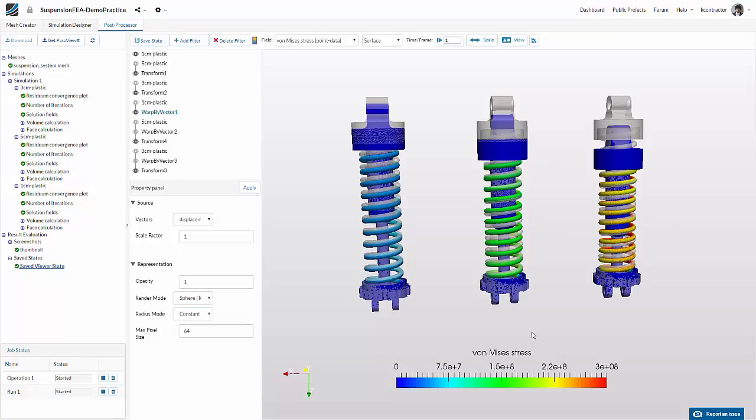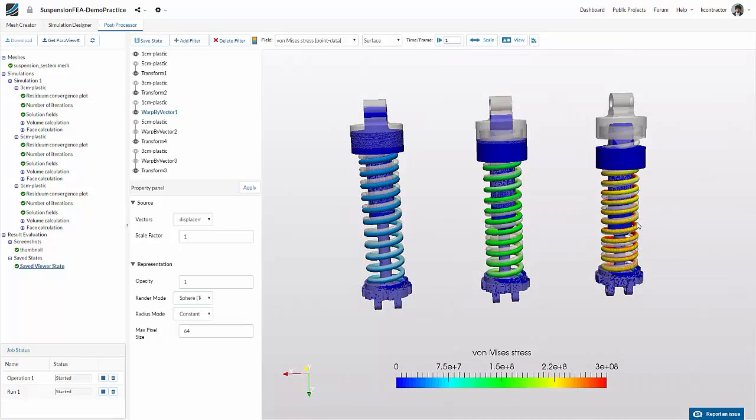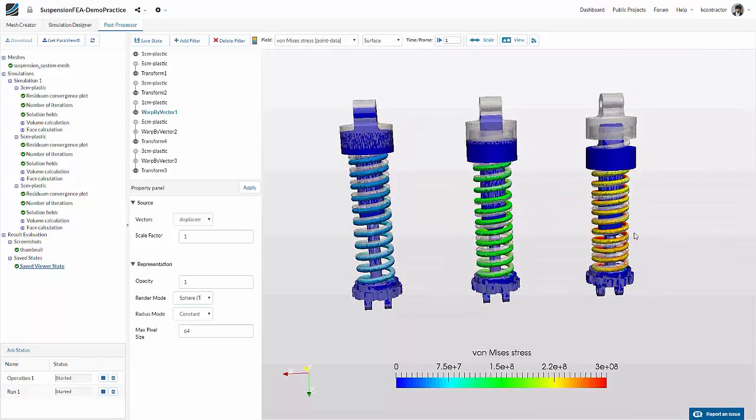This would still not plastify our suspension or our spring. So basically what this means is, if you apply a deflection of 1 to 3 centimeters, it is operating within a safe range, and it would immediately jump back to its initial state once the load is removed or once the load is relaxed.